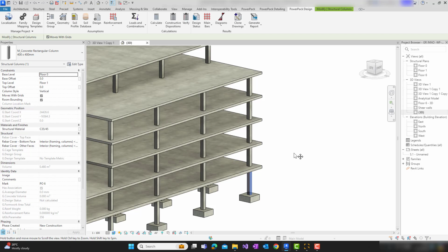Now when we export from Advanced Design, you do actually have the option. For instance, when I was in Advanced Design, I just did the export for the BIM results. If I'd had objects selected, it would actually give me an option to say, do you just want to export the results for the selected elements? So it might be that it's a very big model, we're not interested in all the results that we've generated, so we can actually filter them by selecting the elements we want to export within Advanced Design.